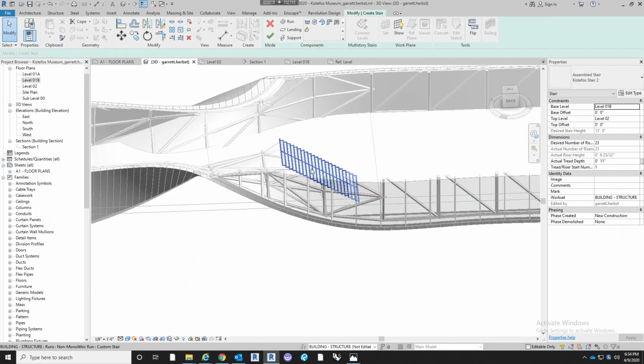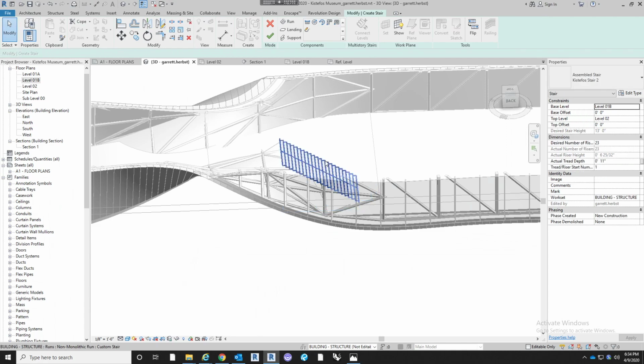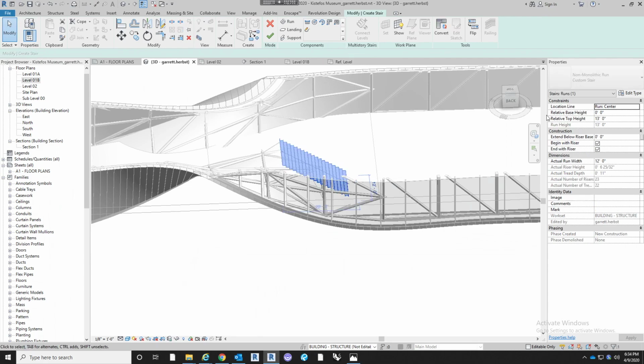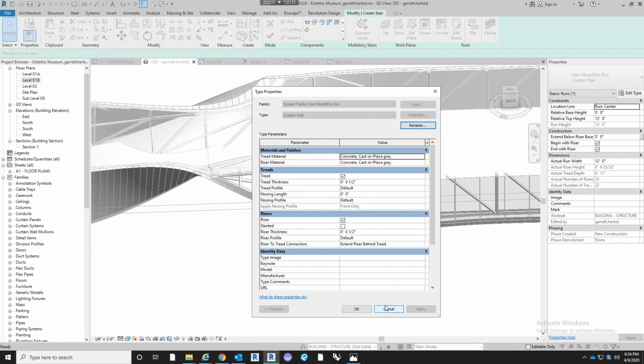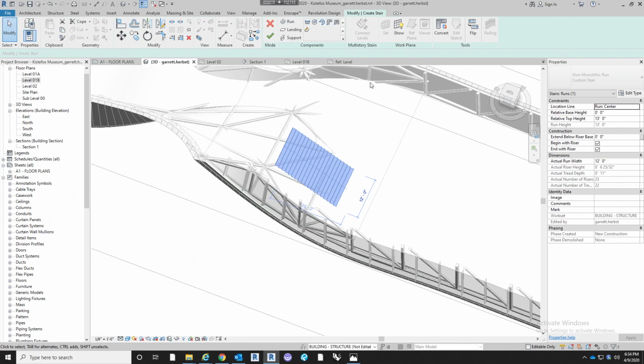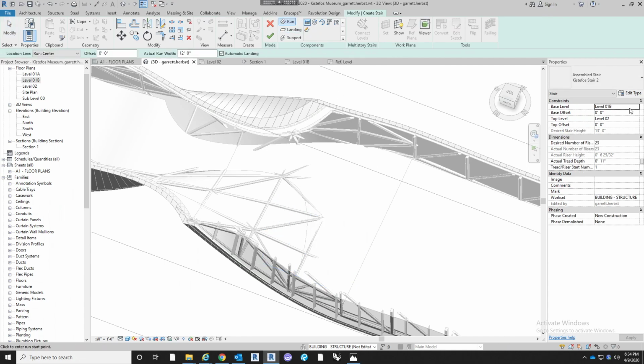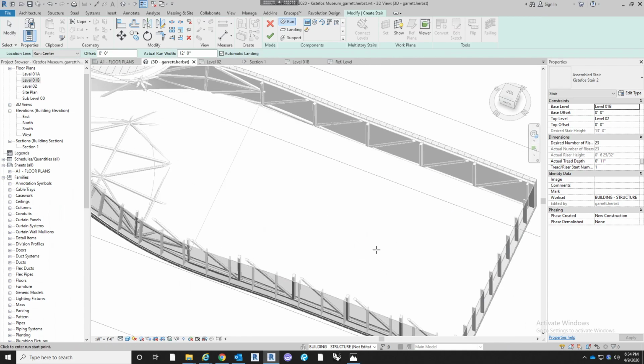Go and edit stair. What we can do is we can change the... where did that go? Oops. Oh, sorry. Screwed something up. A couple things. Let's delete this. Let's go back, hit run, and remember our floor is actually 2 feet above our level, so we have to change it from a 0 offset to a 2 foot offset.